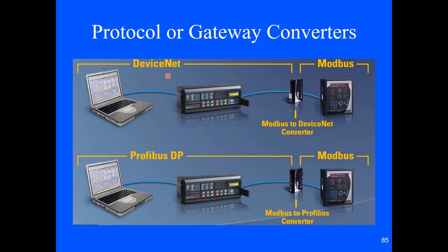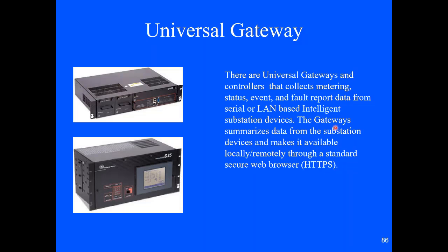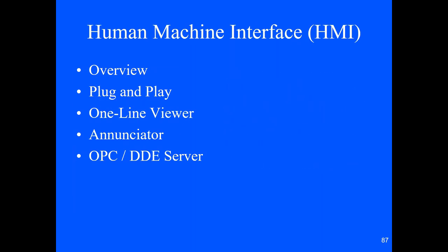There are protocol converters. So I could go from, like, DeviceNet to Modbus or Profibus to Modbus, and you can have that go both ways. There are also some universal gateways. So these devices could actually take 12 different protocols, bring them all in, and convert them all to one protocol. They've got web pages built in and other features.